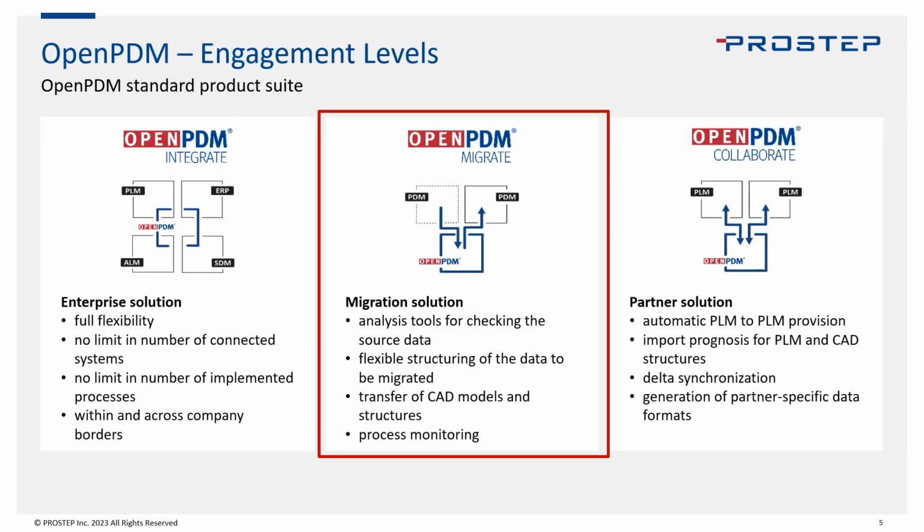So OpenPDM actually comes in 3 different flavors. The one that we're focused on today is OpenPDM Migrate, but there's also OpenPDM Integrate that is an integration platform, and OpenPDM Collaborate that is integration over corporate borders, sometimes to a neutral PLM. And there are shared components between all 3. But when you're focusing specifically on OpenPDM Migrate, you're utilizing all the different connectors that are available within the ecosystem, but then also have special tools for staging databases for an ETL style migration.